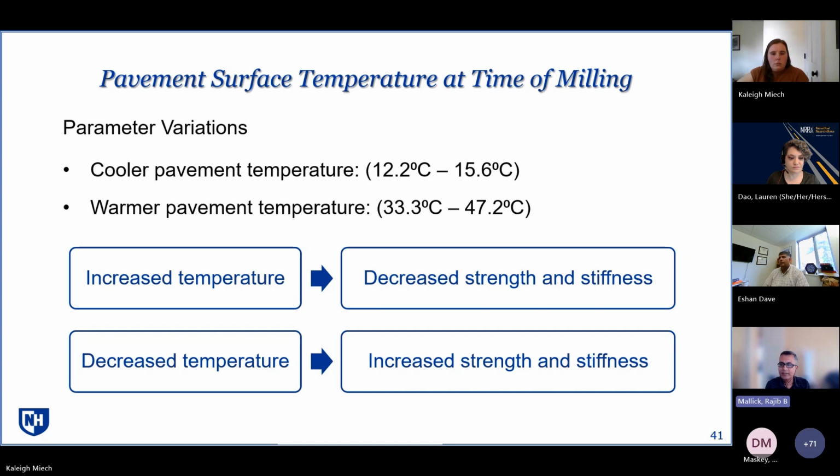Now, what's happening is that if you look at the milling process, you see the teeth are not aligned in the same way. They have a variety of patterns. So there is a randomness in the way the teeth strike the pavement. And why is the temperature important? Because as it gets cooler, the material becomes stiffer, for asphalt mixes, that is. And as the material gets stiffer, you generate higher and higher stresses in the mixtures. If you have a warm mixture, you can just pluck off the material, so to speak, from the top and not affect the bottom part as much. But if it's a really low temperature, the entire thing gets very stiff. And you create stresses, and you may have hairline cracks, or cracks that are really going to affect your strength. Again, there's a randomness. So I think when you do the milling makes a huge difference.